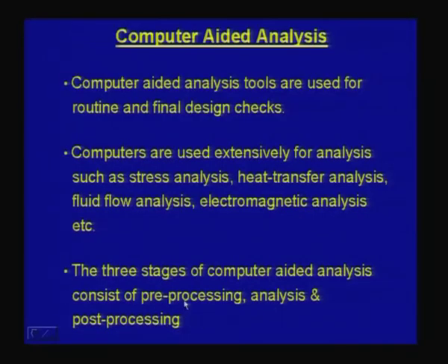As a part of pre-processing, one actually prepares a model, or let us say a finite element model for the analysis, and once the analysis is over, the post-processing is used as an interactive tool to visualize the results. For example, if I am carrying out a stress analysis of a component, then I would like to visualize the stresses, deflections and strains at various locations of this component, which gives feedback as to how to go and redesign the component.